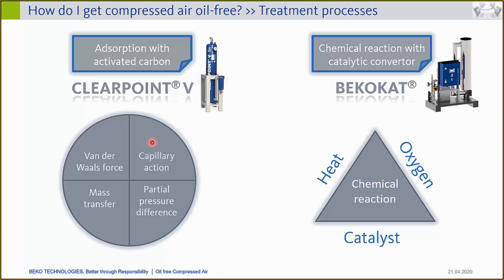The next point is the mass transfer. Mass transfer means that mass is being transferred from one component to another. In our case, for example, it's the mass of oil vapor which is being transferred from the compressed air stream into the activated carbon.